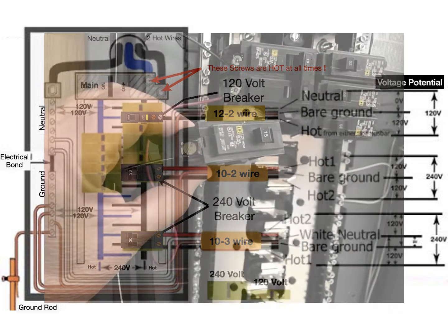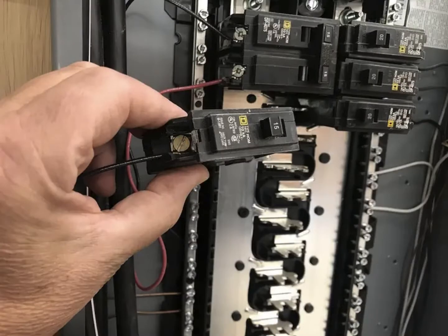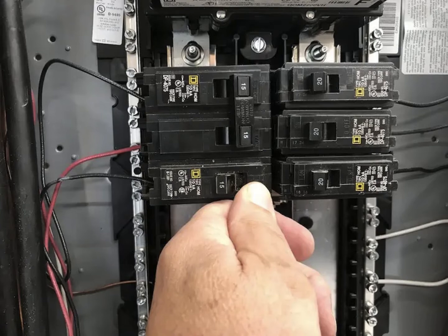With the breaker switch in the off position, install it on the main bus. Many breakers have a hooked outer edge. Slide it into the hot bus bar until it engages. Then firmly push the other end down, over the protrusion on the breaker, until you hear a click.